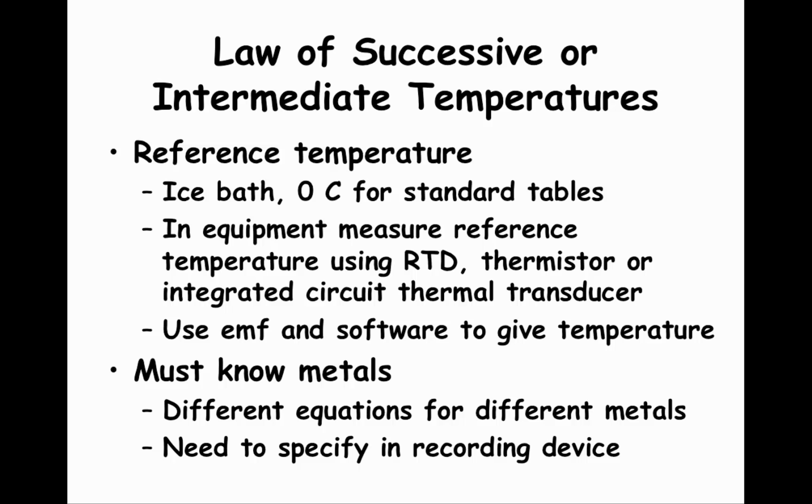As I mentioned before, if you have a simple two-wire circuit and you need an external reference temperature, the standard reference temperature is an ice bath. In the old days, before our modern electronics, there were standard reference tables that listed the EMF for each temperature, typically down to 1/100th of a degree Celsius.